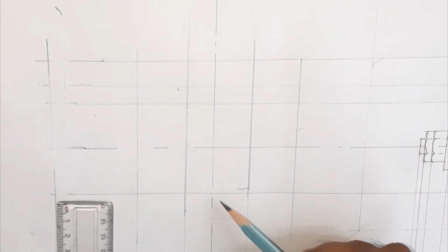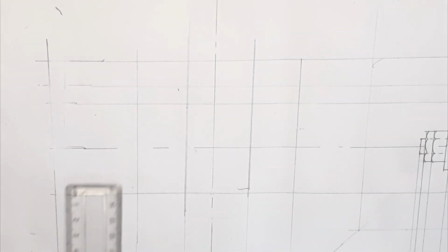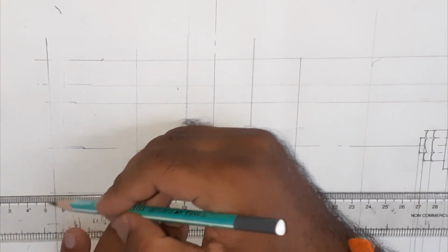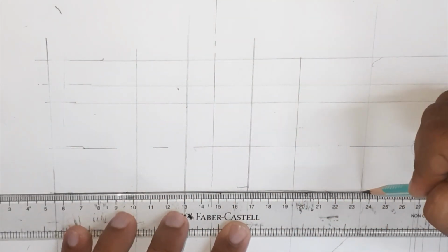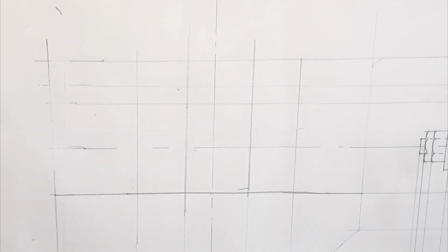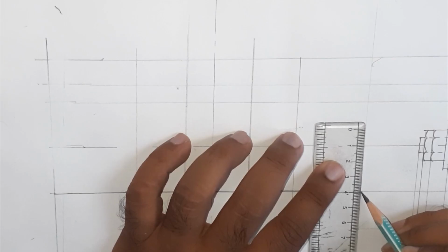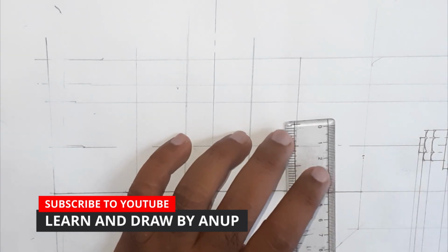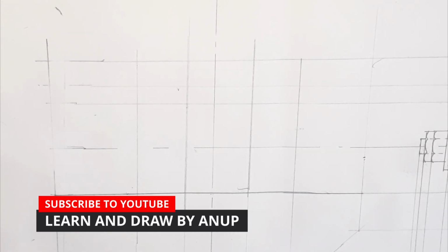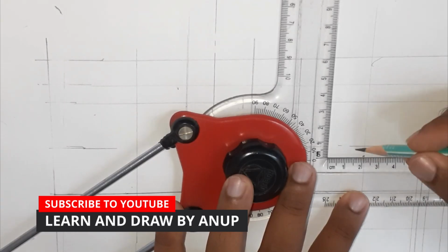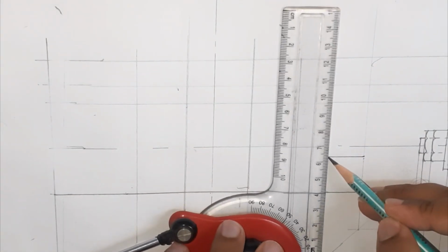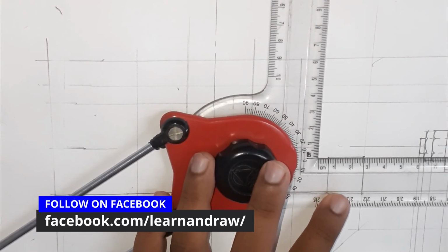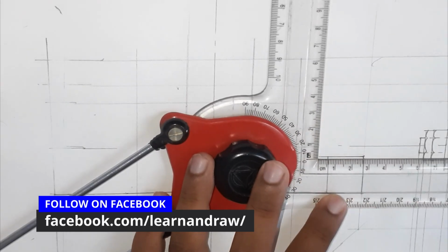So here you can see, this is the axis line, and this is the end of this one. Let's first draw this line. So this is the first line. Next, the second step is we have to draw the height of 23 mm. After this, we have to draw a line of length equal to 21 mm and complete this box. Next, extend this up to 26 mm. Like this, draw a line up to 26 mm.